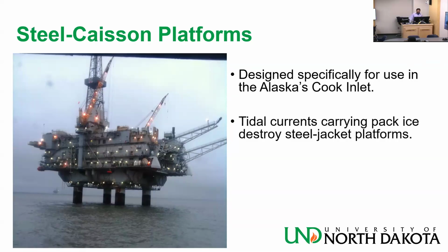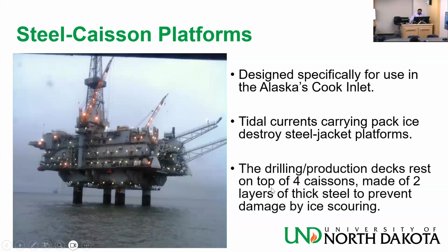Tidal currents carrying pack ice destroy the steel jagged platforms. The drilling production deck rests on top of four caissons made of two layers of thick steel to prevent damage by ice scouring. So those caissons, yes, they are concrete, but you will have steel around them to be able to handle the friction with the ice, which is worse than friction with water or anything. It's like a very bad abrasion that you can have with ice.